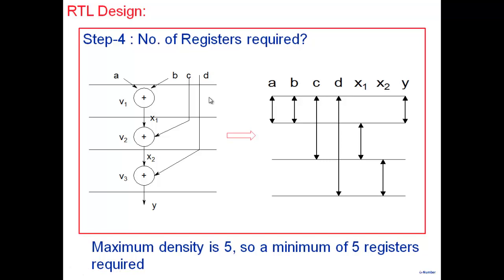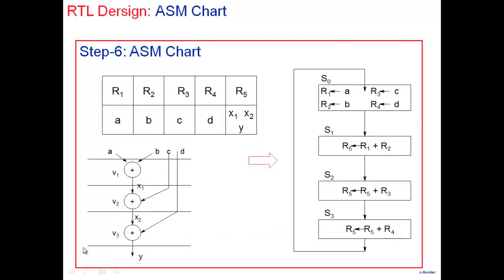What we had implicitly, in all this discussion, is that there is a load required here. So implicitly what we had in this particular diagram was a sort of loop pipelining assumed. Because note that if I add before this a load cycle here, where I read the data, where would this be available now? In the read part, right? So where the confusion was: all these diagrams are correct, but they imply that I will eventually store Y in this particular cycle. So as an intermediate step, we said, okay, we need to add this. But remember that this is sort of a redundant state.